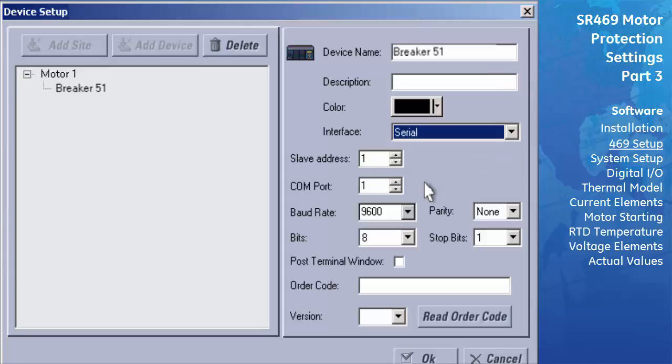the menu. Several new fields will appear in the area below. The Modbus slave address is used to identify specific devices for communicating on the network. When communicating through the front port, there is only one device on the network. Therefore, there is no risk of communicating with the wrong device. For this reason, we can leave the Modbus slave address to the default of 1.